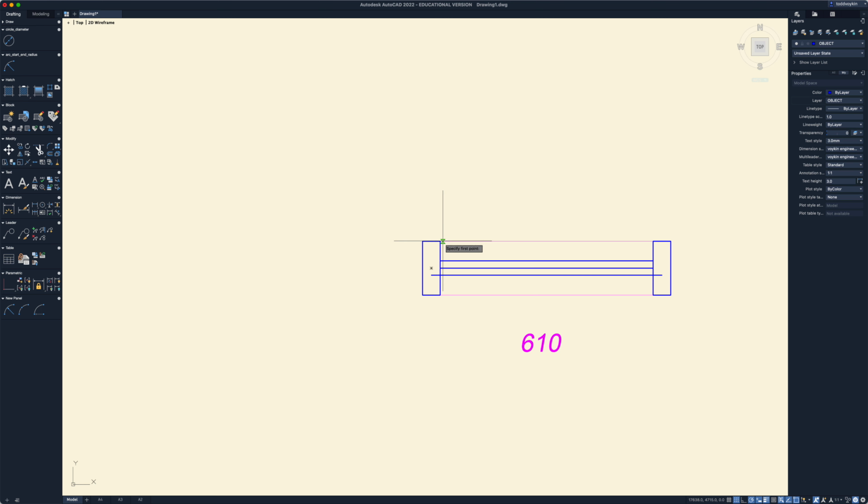So we'll take the line off of this point right here. I'll go out 200 and I'll slide over this way. I could type 610, or remember I can just hover over that point, and that will give me an indicating line of where it goes.